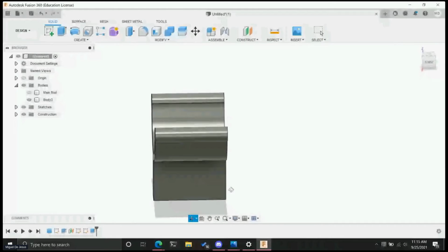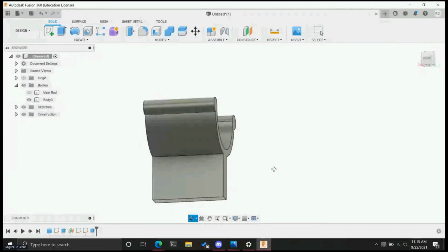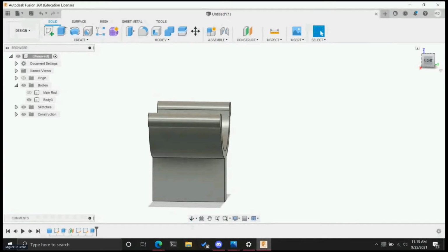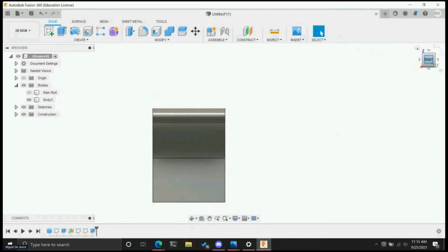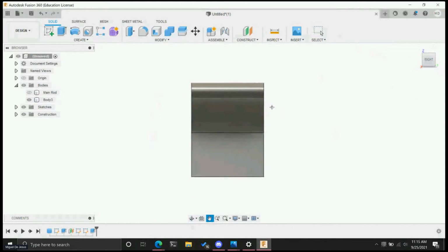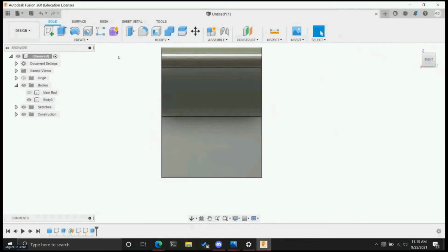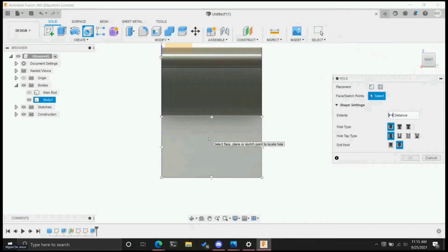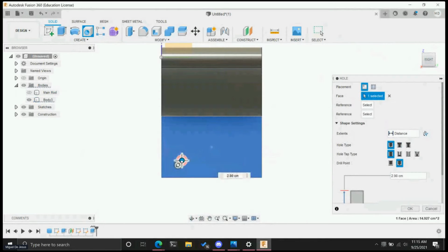That's cool. Now if I'm gonna mount it down here, I want to put a couple of screw holes in there, right? So if I press here, then you can make it completely be on the side, which is going to make your life easier. There's going to be a button here for hole. If you press it, you can select a face that you want to put the hole in, and then the location of it. I'm going to put one of them here, and then the size, well, the size that I had before seemed okay.